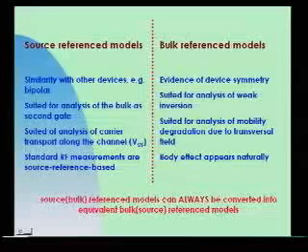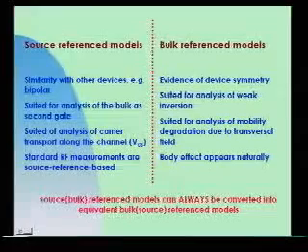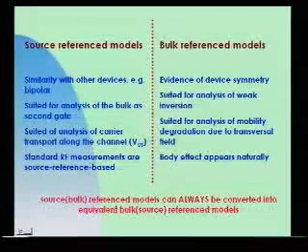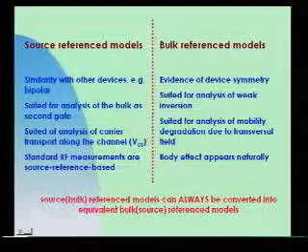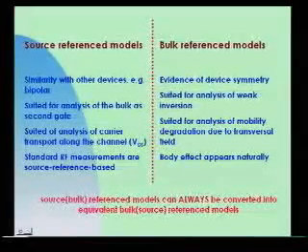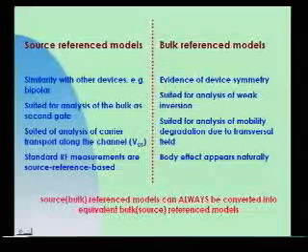As advantages of the bulk reference models, we have that the symmetry of the device is more evident. It's emphasized in the bulk reference model. The symmetry concerning the interchanging between drain and source.